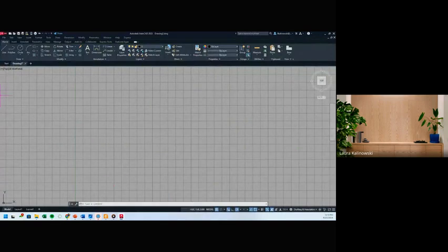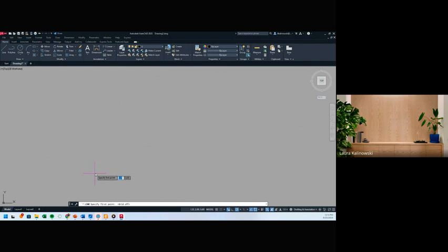So going back to CAD, up under the Home tab is my line command. And you can see that this is where our coordinates are. As I move my mouse, the coordinates change. So I'm just going to start, and it does not matter where. In fact, I'm going to turn off my grid mode here, my little tic-tac-toe, and I'm just going to draw out. And it doesn't have to be perfect. I'm not looking for perfection, but draw out a star.